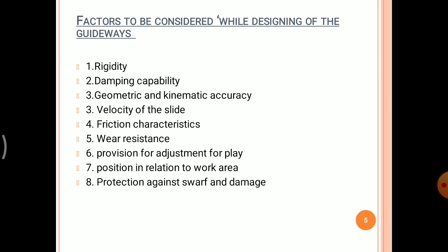In the guideways, there should be a provision for the adjustment of play, adjustment of the spindle bearing, and checking whether the spindle is rotating correctly or not, whether there is any run out. That we have to check by using the adjustment of play.